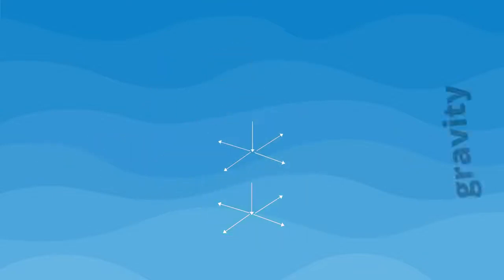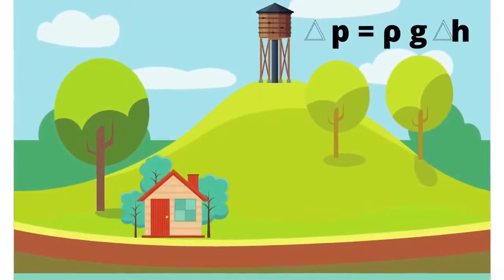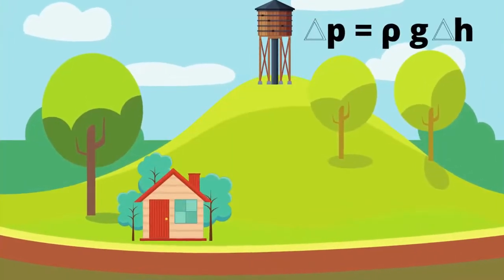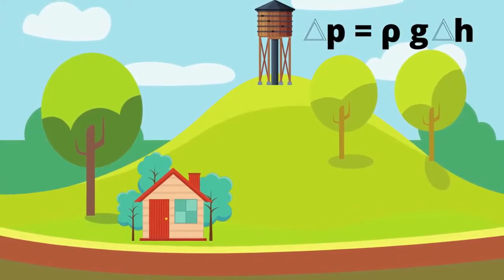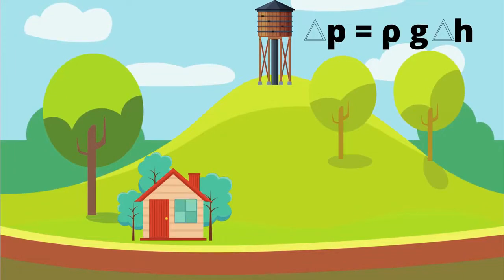The principal equation is that the difference in pressure equals the density of the fluid times gravitational acceleration times total height. As for the application in a water tower, we can assume that the density is constant as we use water, and the atmosphere is also constant.